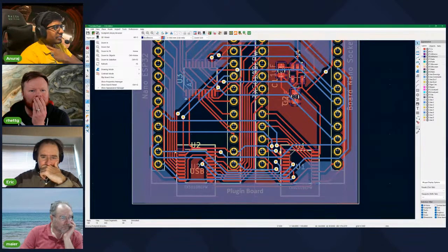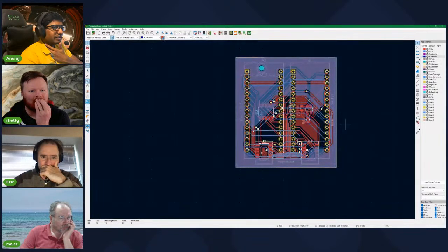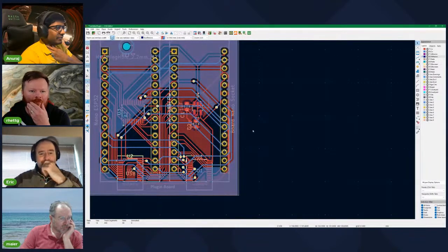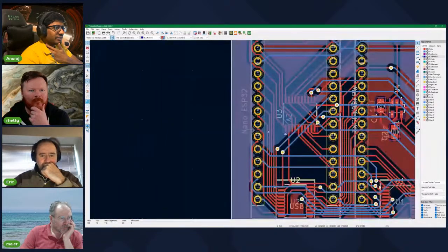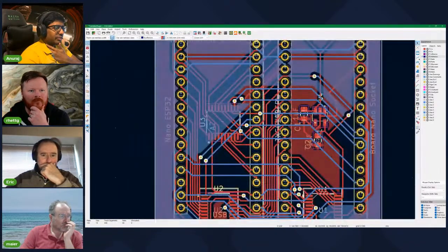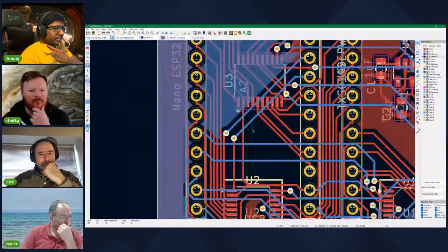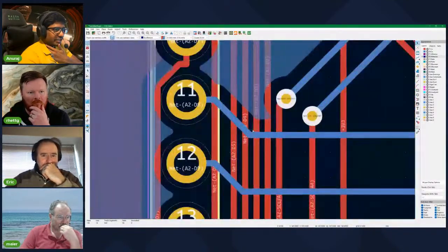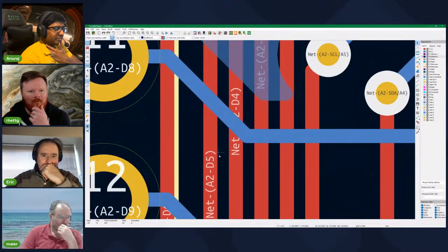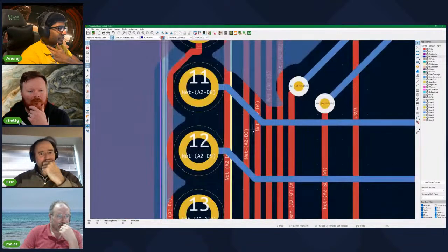Yeah, I'll have to search. So there is a board, basic board defaults which I use. It will set the thickness of these routes and the distance between them. When you are routing these lines, you need some tolerances between them. So that is also set.